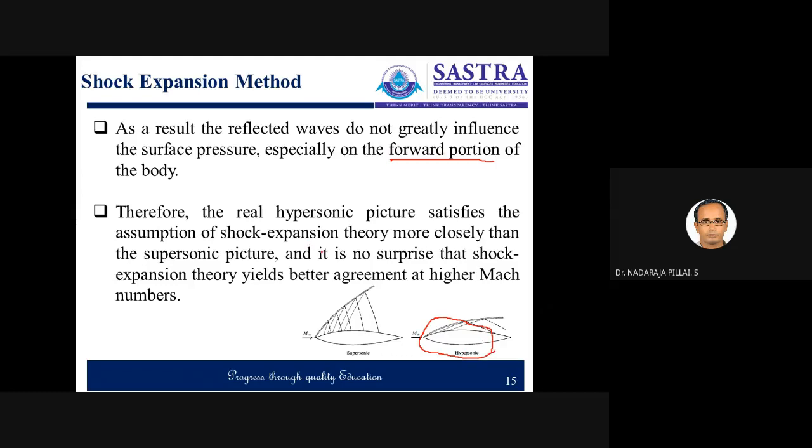Therefore, the real hypersonic picture satisfies the assumption which we make in the shock expansion theory, right? So it will have a good agreement with the characteristics, right? So if the Mach number is very high, the shock expansion theory predicts better when compared to the supersonic Mach number, right?